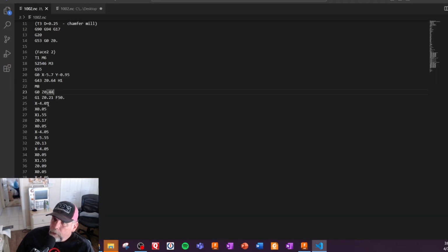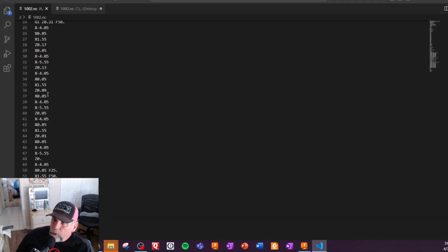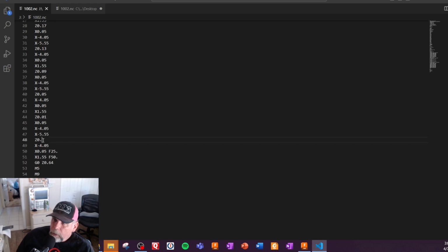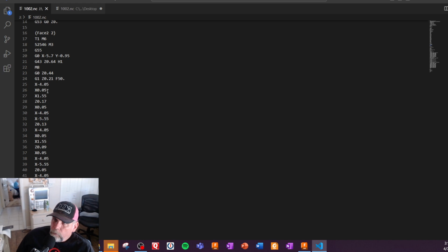All right. I go down the list and I look through all the cuts. And the last one is 0. I always look for that. And this is going to be cutting at 0, and the last move is going to go up. So if you follow along here, I'm making my first cut at positive 210. Remind me, we're always talking in thousandths as a machinist, so 3 digits, even though these are rounding off.